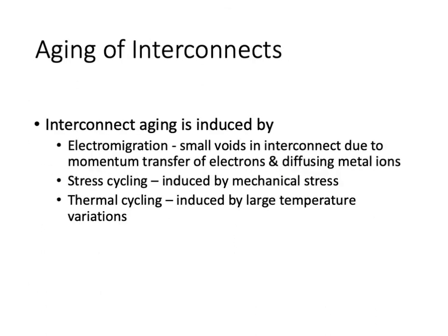There are also aging-induced degradations of the interconnect, the wires. And the primary mechanism for these aging effects is a phenomenon known as electromigration. So as the wires are always conducting charge, you're applying electric fields, turning off the electric fields, applying electric fields, turning off the electric fields.